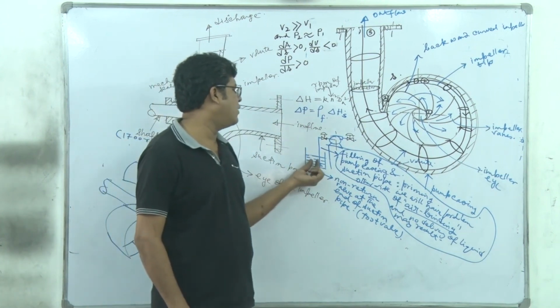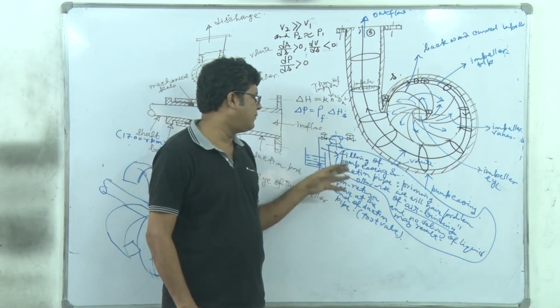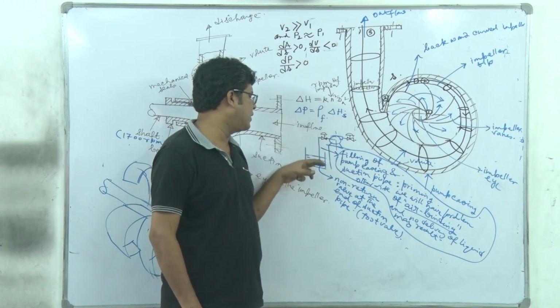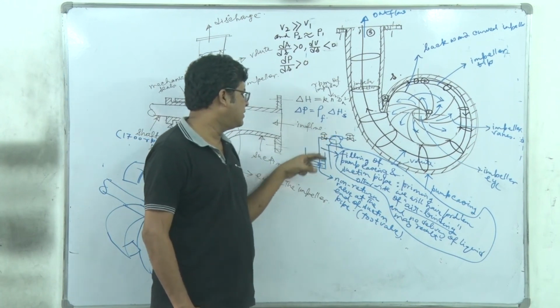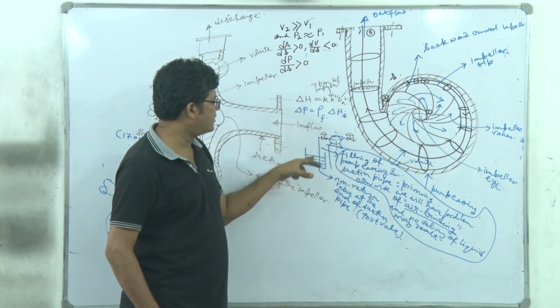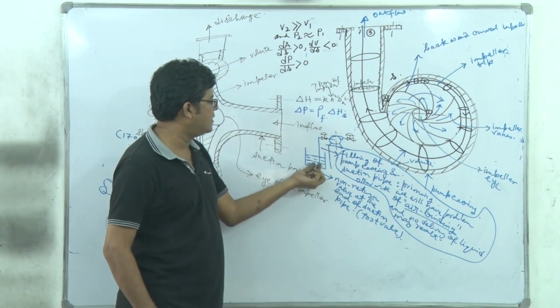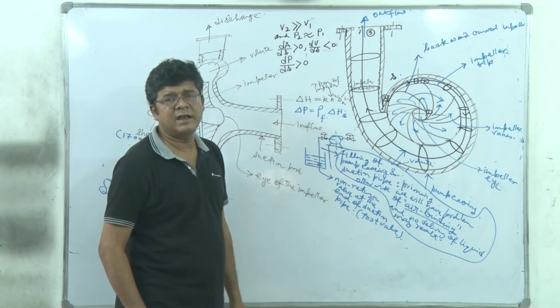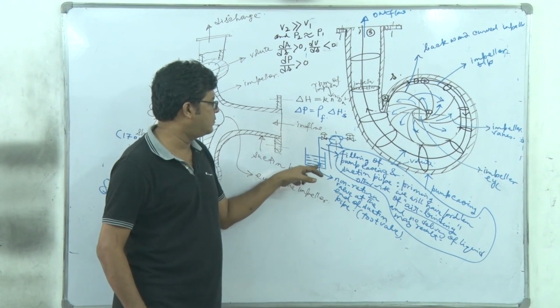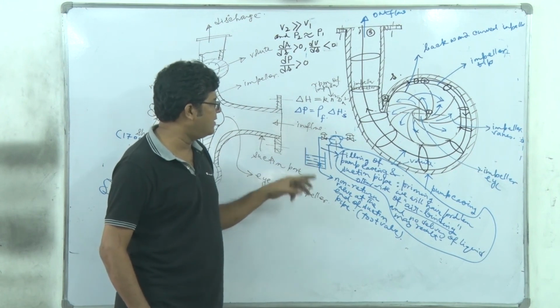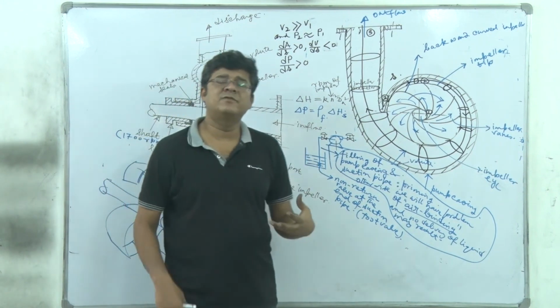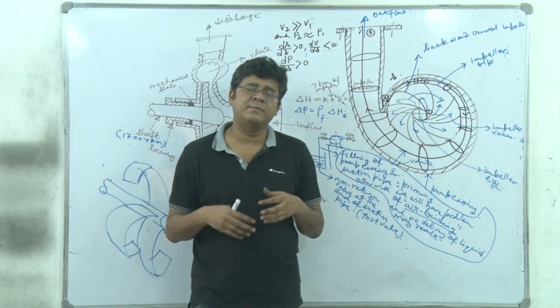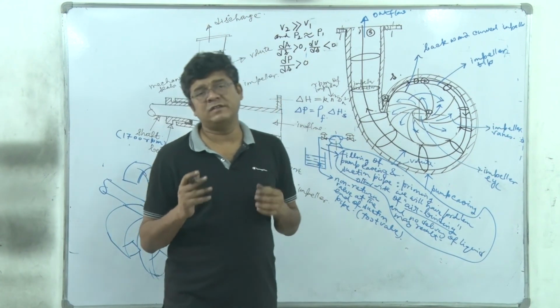For a common household pump, we have to prime it at the point of installation, and we ensure the liquid is present in the suction line and the pump casing by inserting a non-return valve at this pump end or the delivery line's end, right? And in larger pumps, we have to progressively prime the pump prior to its startup.